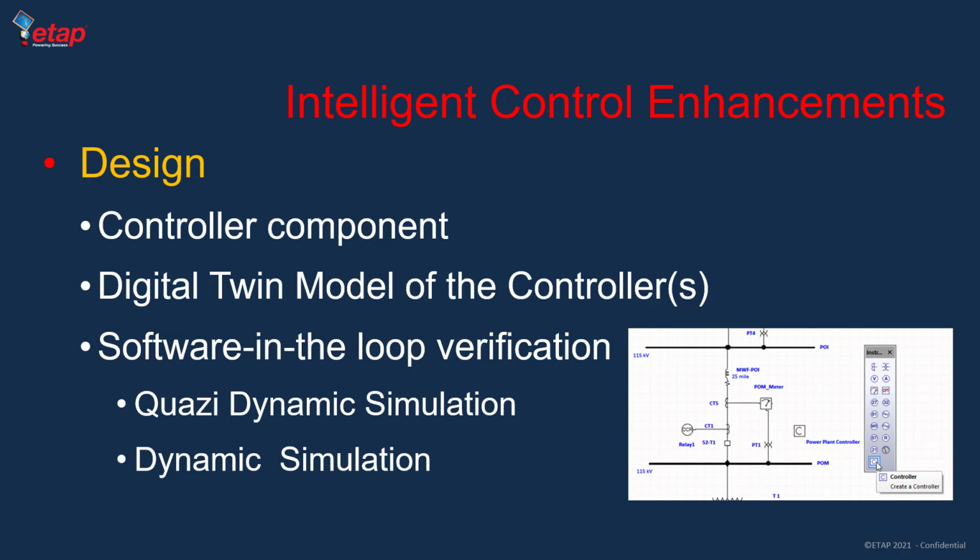The controllers have been handled in past years as projects, and the elements and functionality were hidden from the users. Now we have decided to provide you access to it. On the design side, we have added the controller component, which can be defined as a microgrid or power plant controller. It has a built-in digital twin model to perform design and software-in-the-loop simulations in a quasi-dynamic mode through the time domain load flow, and dynamic simulations through the transient stability module. The main difference is the time step and the validation you want to perform.